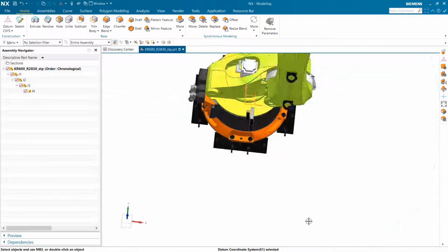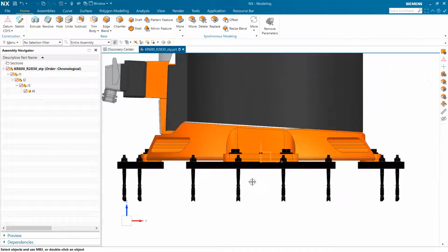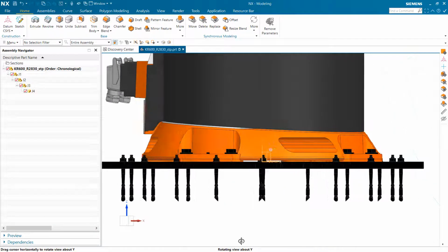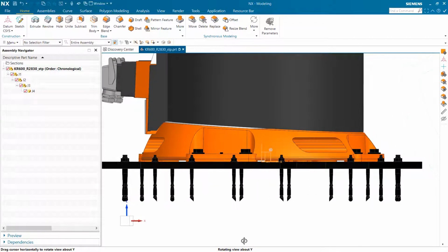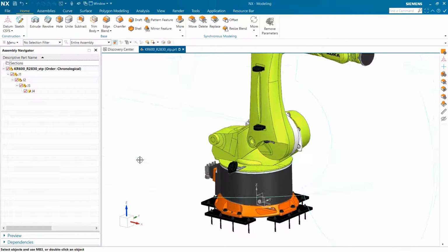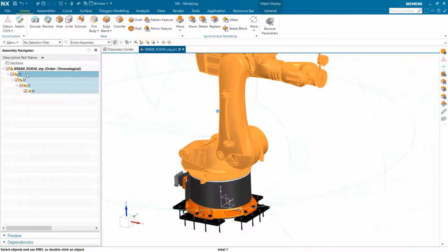And when I try to check the position of my robot, just to make sure that the robot is actually sitting at the 0, 0 position as currently shown. So you can always reposition your graphics so that it is actually sitting on the 0, 0. This is actually a very convenient way to do it here, because once you're in the plant simulation environment, it is very difficult to identify the coordinates.